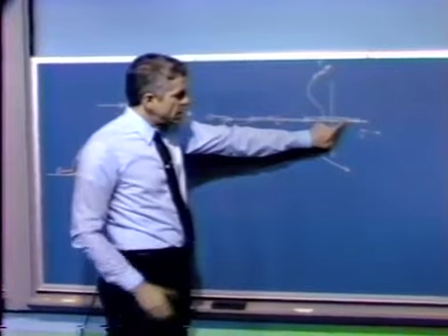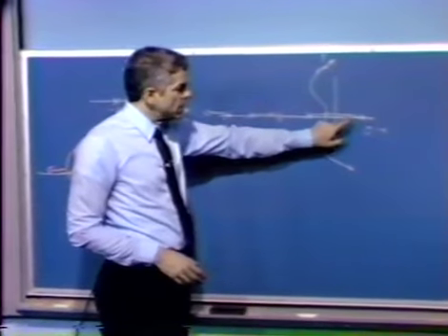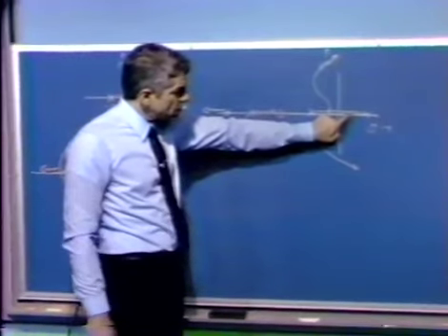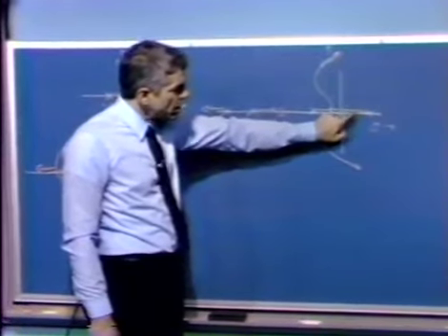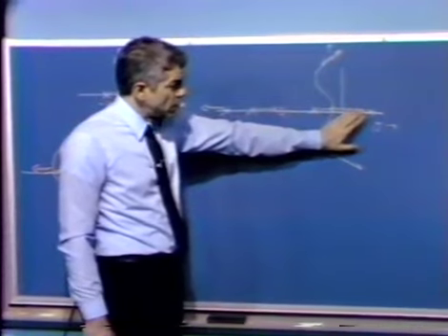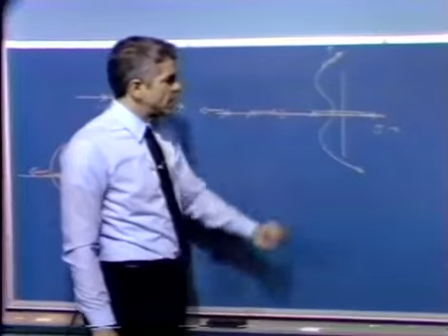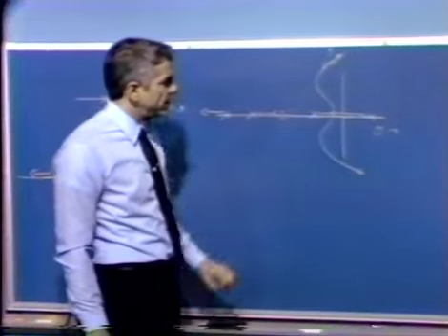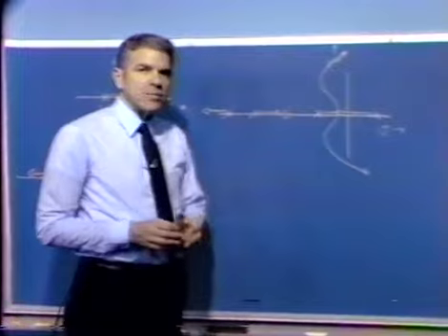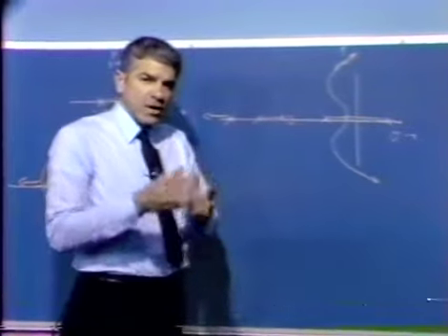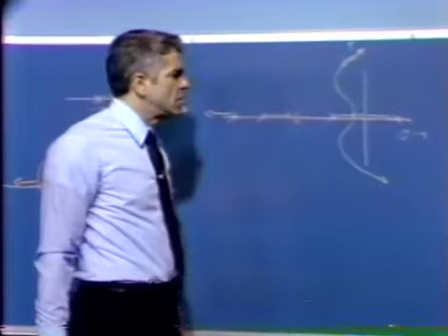In other words, that's the sort of single exponential growth, and what that tells us is that we haven't increased A naught sufficiently. We're still at the point where there's a pole associated with the system in the right half plane. We have a real exponential growth away from the equilibrium point. You can feel that. The ball just sort of tries to drop out of the field or tries to pull up into the magnet as you let it go.